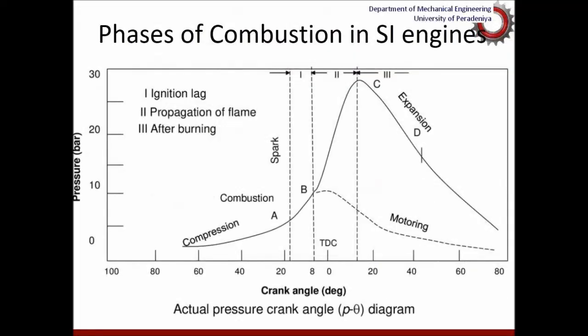In the last lecture, I explained the combustion in spark ignition engines. In general, we have identified three different phases in this pre-mix combustion process. Initially, we have this ignition delay period or ignition lag period, and then we have this 10 to 90% of burning phase, that is the flame propagation phase. And then the last 10%, that is more or less the after-burning phase, where you expect the last 10% to burn.